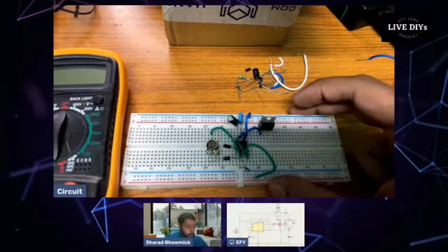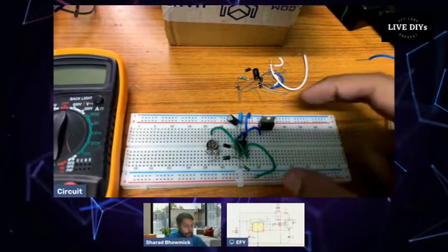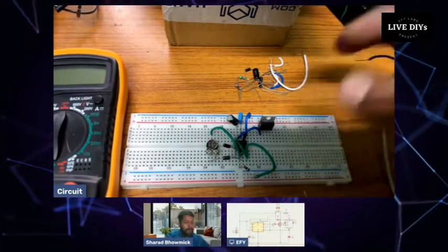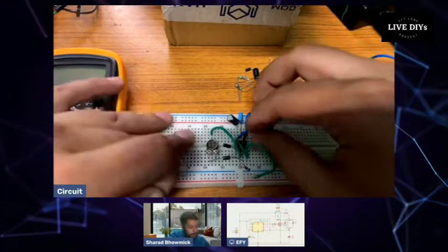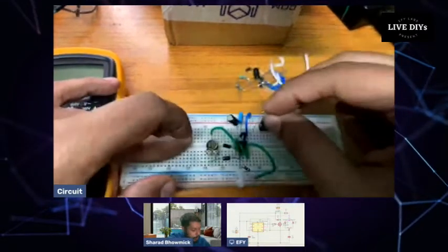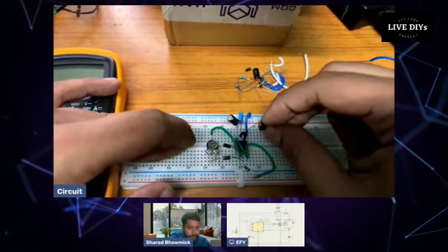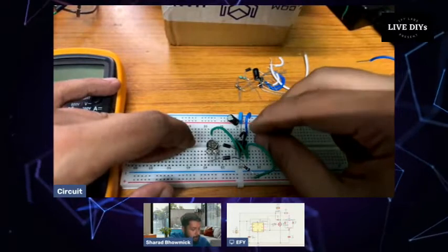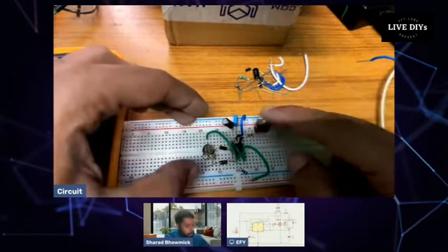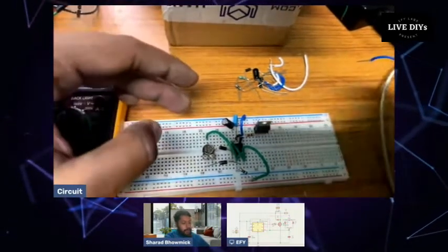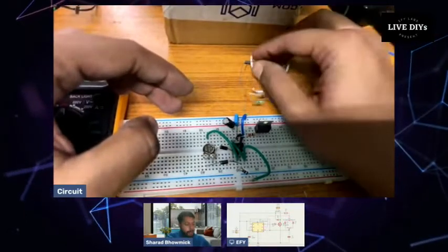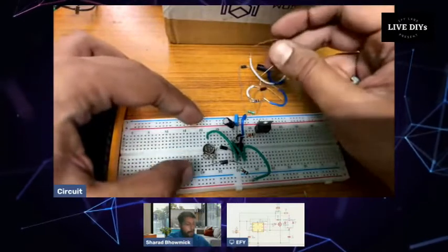Now what else do we require? I think we missed a 200 ohm resistance that was used for connecting the gate. We basically connected this thing with a wire, but we should have used a resistor to control the current. That is the gate with the third pin where we are controlling the output. Now we also need to connect our MOSFET with a reverse diode, if you're using it for controlling a motor, because we don't want the reverse current to damage our MOSFET or our switch.